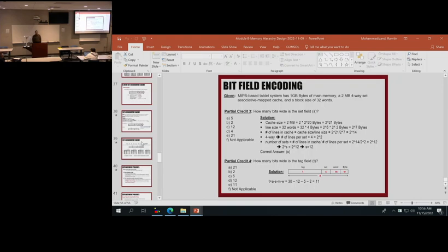The address bus finds it in the memory. You do have the row. So in the memory, if you have a row selector, you have a row decoder and column decoder. These are the things I didn't talk about because it's a circuit kind of thing. So those decoders are responsible for finding the specific line in the cache. All of these bit cells that I have in the cache have lines that select them. So we have bit line, source line, word line, and so on. So basically the address goes to the decoder.